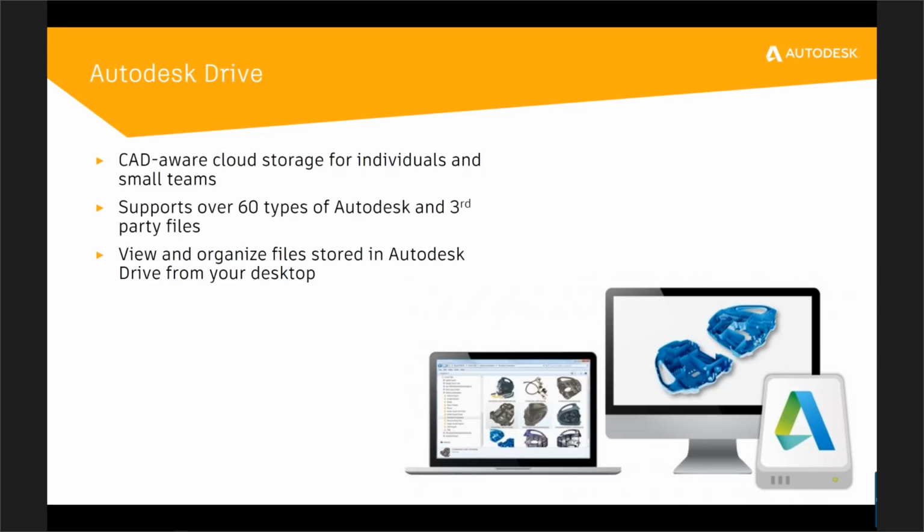Unlike things like Google Drive or Dropbox or what have you, this is Autodesk hosted and it's CAD aware. What that means is if I were to drop a DWG file with XREFs in this, it would say, hey, those have XREFs, and it would grab them. It gives you the ability to access your Autodesk cloud storage as if it were a network drive on your computer. So when I'm going through Windows Explorer or standard save as dialogs, my Autodesk cloud storage appears as a standard network drive. I have access to that data as long as I'm connected. So it's not syncing; I'm actually working live off my cloud data for my desktop product.